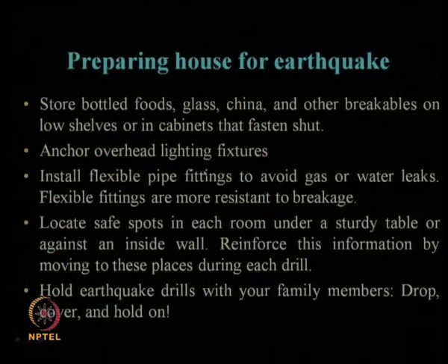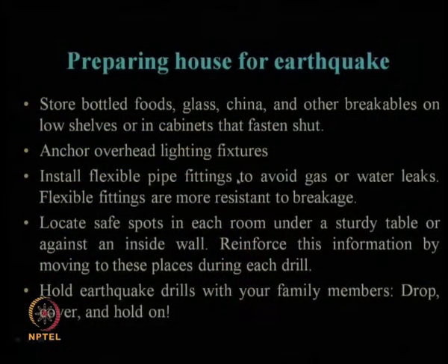Anchor overhead lighting fixtures. As I have already mentioned, all the electrical fixtures should be fixed properly. So, it includes your lighting fixtures, which are typically overhead. Even in our Indian conditions, ceiling fans etc. need to be fixed properly, so that during the shaking process, whenever an earthquake is coming, the ceiling fan from the overhead will try to swing, because it will start to act like a pendulum system. So, there is a high chance that it can fall or come down if the connection is not proper. To avoid that, one must connect the overhead lighting fixtures and ceiling fans properly to the